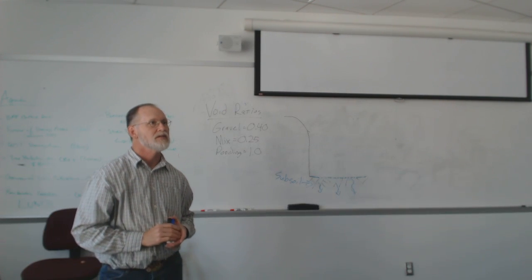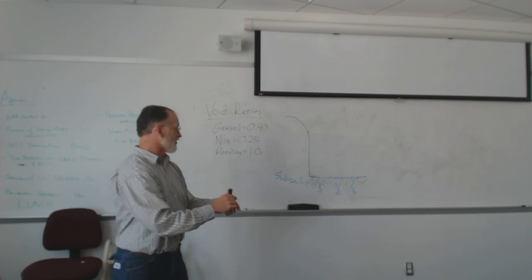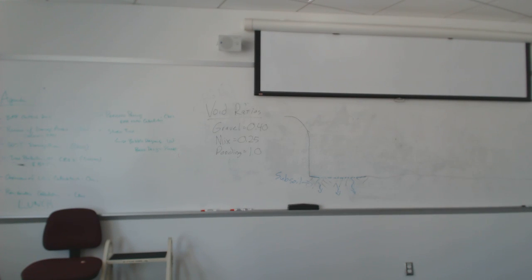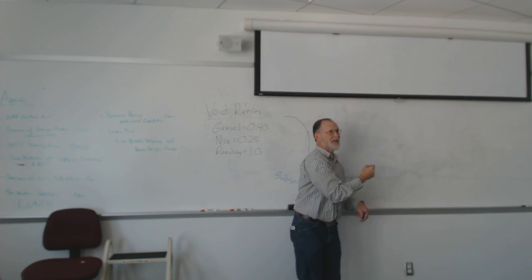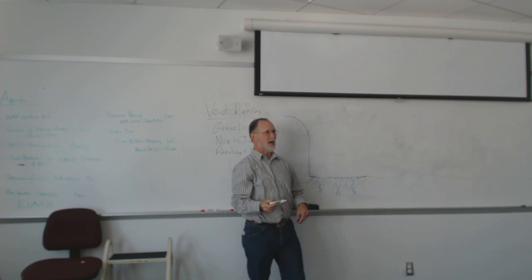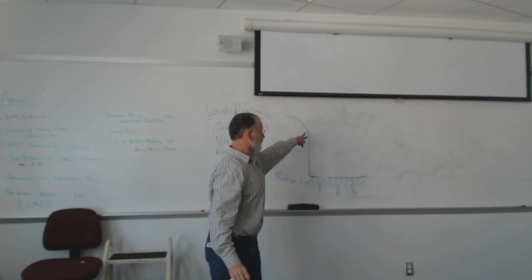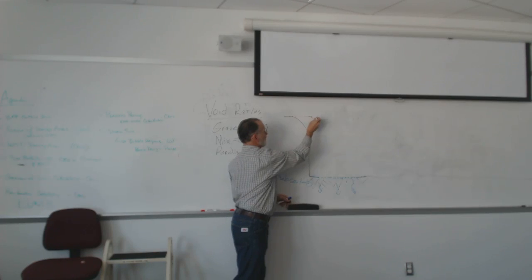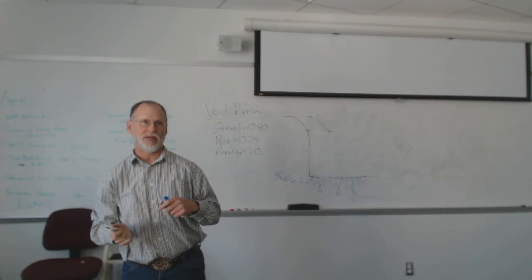Yeah. So I'm guessing the same goes with the side. The sides don't really matter. Okay. Because if you remember with our correction thing that we did, our rain gardens tend to be really big. Even if it's like a dry swale, if you've got a swale and you dug it, normally when we dig it, I want as much bioretention mix as I can. I want as much volume as I can. So it's typically going to have straight sides. Actually, when we dig it, we kind of dig it like that, and then we'll ramp up the bioretention mix or put gravel or something there to give a smooth transition.